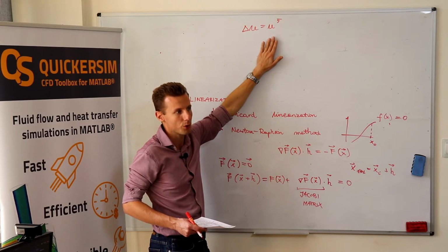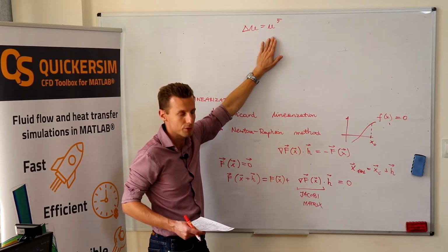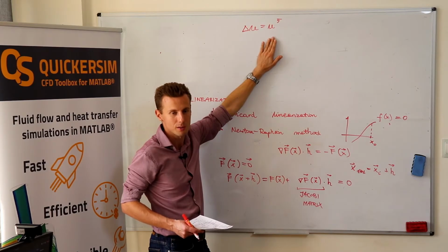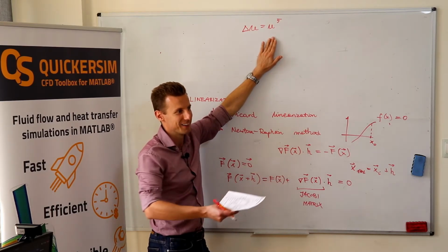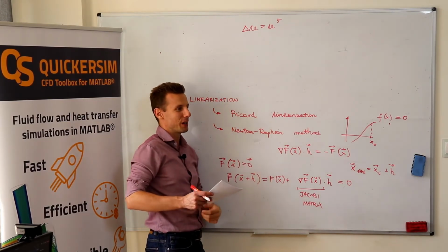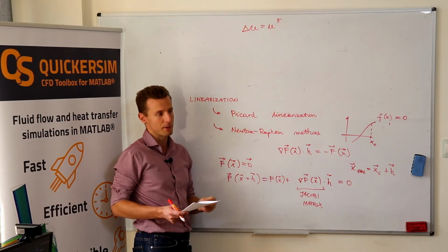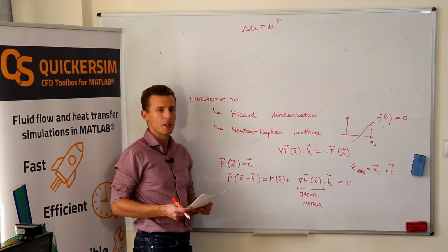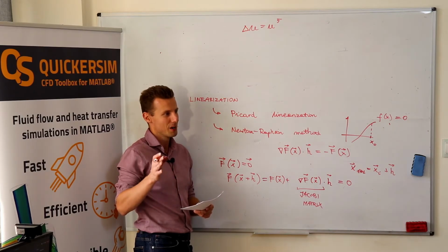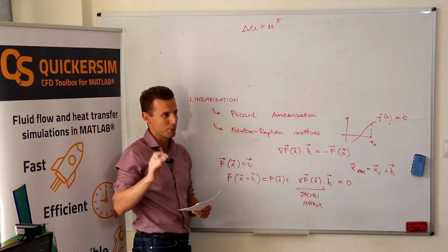Or if you want to converge, what can you try to do if your iterative process diverges and you want to make it convergent? Yeah, under relaxation is a cure for everything, but not a very nice or effective cure. But it's one of the ways. But I would suspect that if you deal with some highly nonlinear chemical kinetics, maybe some evaporation processes that almost do not take place until a certain temperature, but once they start taking place, then you go like a couple of degree range when everything evaporates.